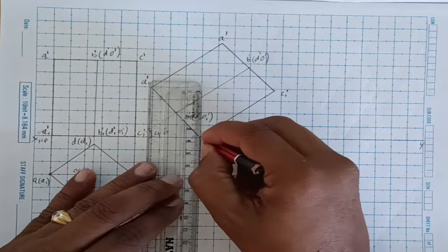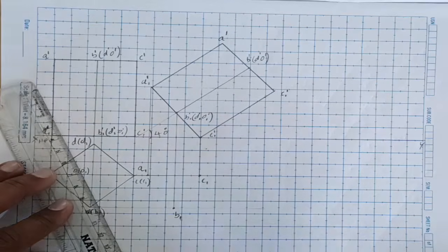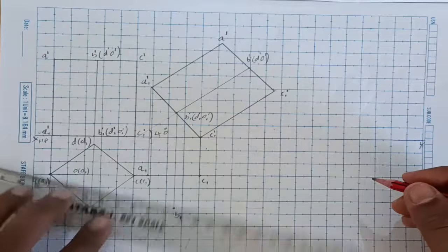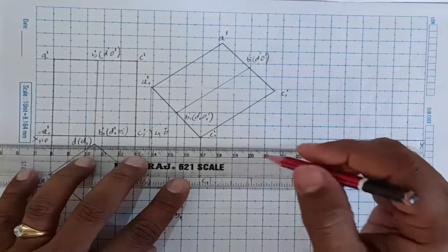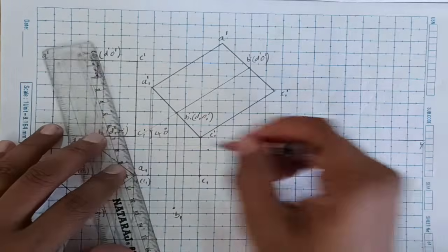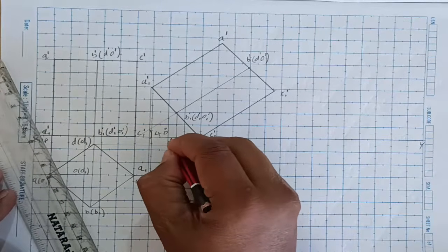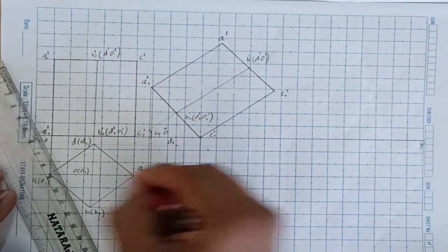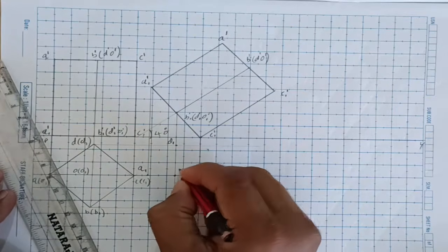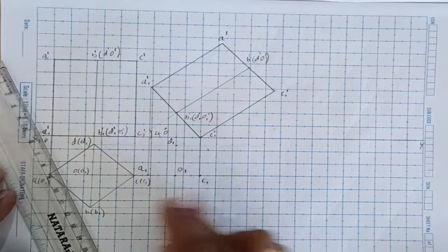If you draw the line to this, we will get C1. And next D1 is here. You can draw the horizontal projections from here and then draw the line. Already the line is there, so this point will be D1. And the center is on the same point of this. This is O1. So like this A1, B1, C1, D1 and O1, we got the bottom face.